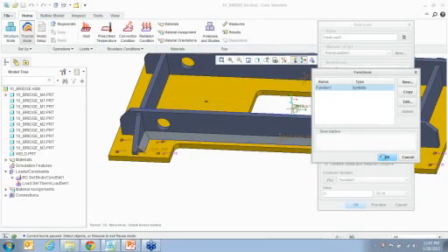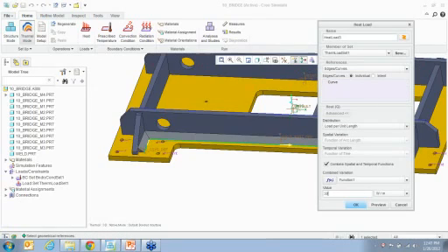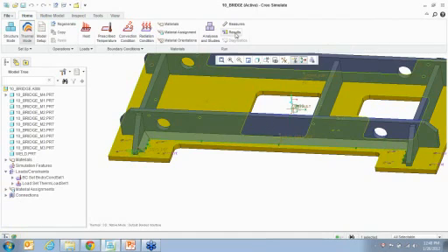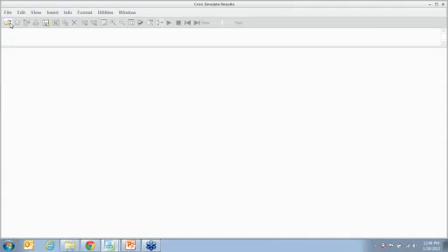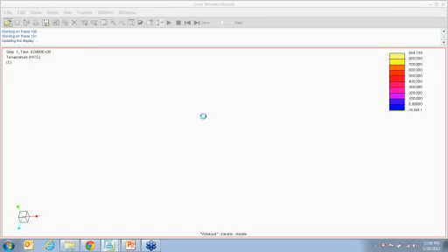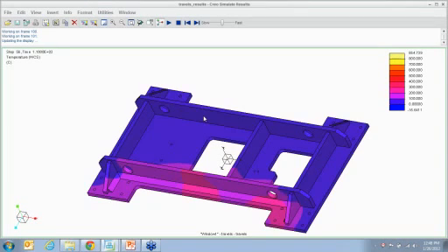Okay, and then say the value of the heat load is 30,000, and we can run an analysis based out of that, and you can look at the result that you get as to how your heat load travels with time and how the temperature is being distributed throughout the part. So you can see how that's your weld that travels, and you can see how the temperature is distributed throughout the time.